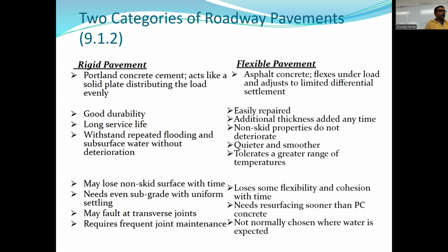On flexible pavement, you lose some flexibility and cohesion with time. You do need to resurface that much sooner than the PC concrete. But it's cheap to do, but you have to do it more often. Not normally chosen where you expect a lot of water. So if you do put them anywhere, you have to make sure that you have good quality drainage.